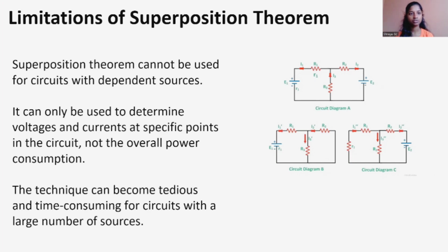Limitations of superposition theorem. Superposition theorem cannot be used for circuits with dependent sources. It can only be used to determine voltages and currents at specific points in the circuit, not the overall power consumption. The technique becomes tedious and time consuming for circuits with a large number of sources.